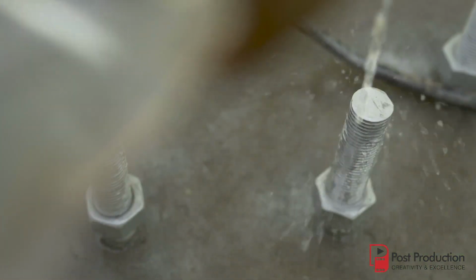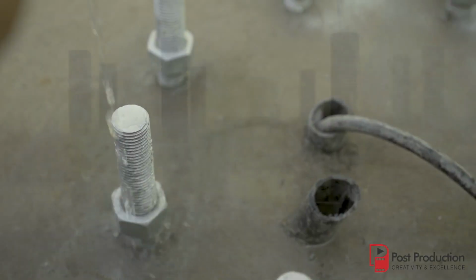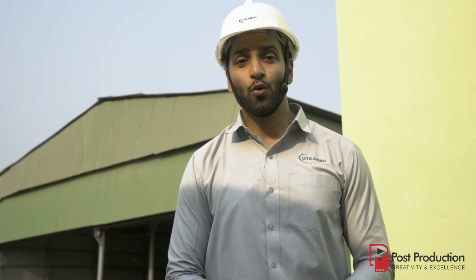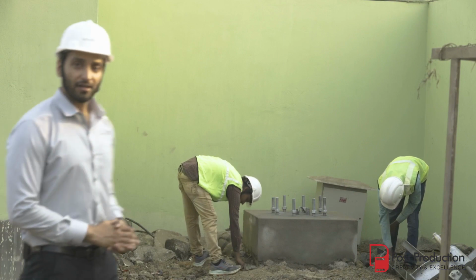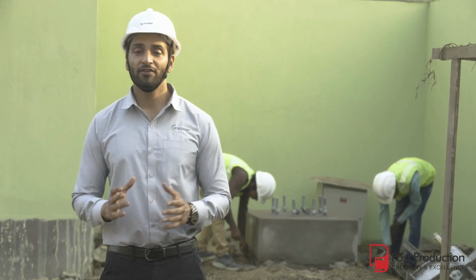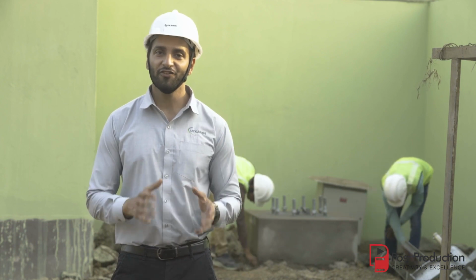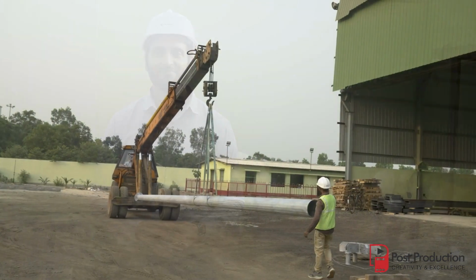Whenever the cement concrete is ready, we have water filling it for making it more strong and solid. As per standard, water filling must be performed for at least 21 days to build it strong and solid. It is the last process of civil foundation work where we have to backfill the extra dig area and finish the civil foundation work.